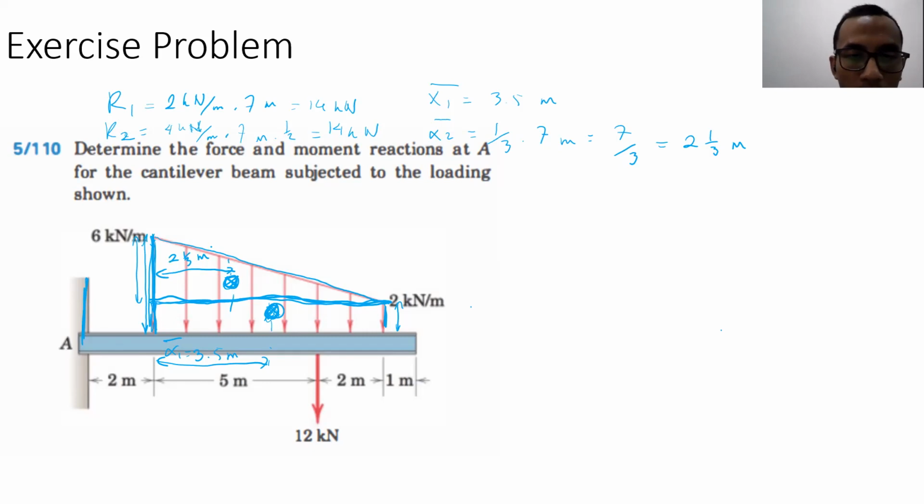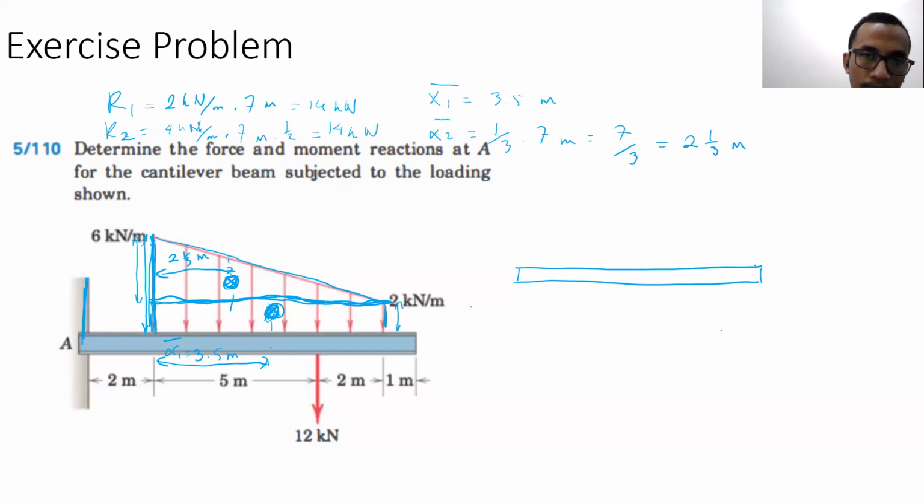Okay, now we draw the free body diagram. Drawing the free body diagram, which on point A we have a fixed point, sir. So it should be only AX, I guess. No, fixed is not just AX. AX and AY. There is one additional thing. When you have a fixed boundary condition like that, you will have moment A.